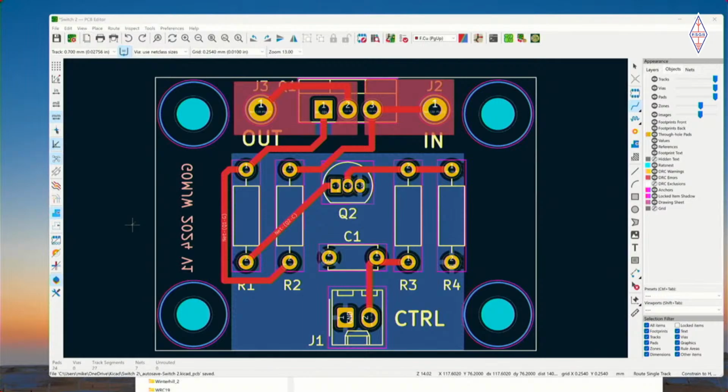I haven't got any example data sheets to hand, but typically a component will, especially an RF component, but also a lot of surface mount components will have a suggested layout as well. So they won't just have the component, but they'll also say where they suggest you put the capacitors and the inductors and the resistors along with that as well. Okay. Lovely, thank you.